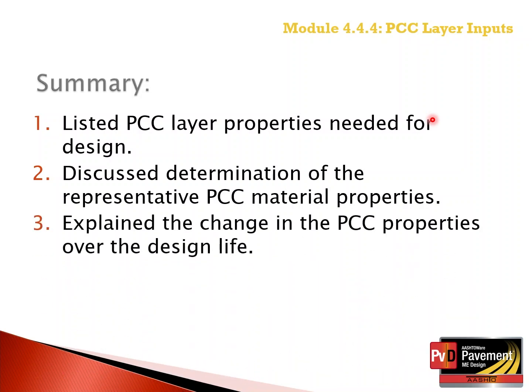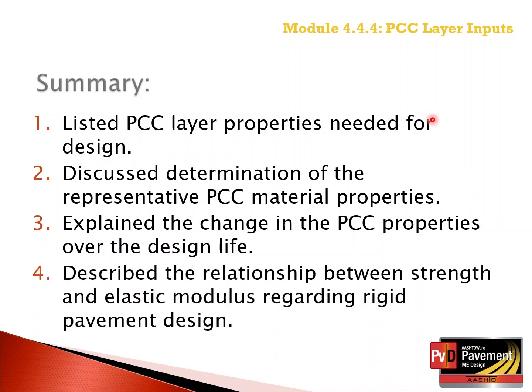The third is we explained the change in the PCC properties over the design life of the concrete pavement. And the fourth and last is we described the importance of the relationship between strength and elastic modulus regarding rigid pavement design and whether the laboratory measured values can be intermixed with the values used through the regression equations embedded in the PMED software.